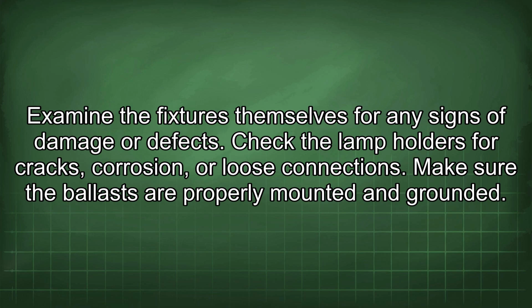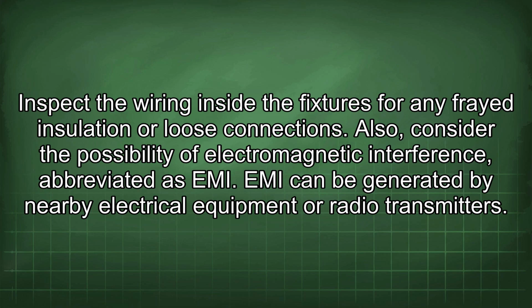Examine the fixtures themselves for any signs of damage or defects. Check the lamp holders for cracks, corrosion, or loose connections. Make sure the ballasts are properly mounted and grounded. Inspect the wiring inside the fixtures for any frayed insulation or loose connections.